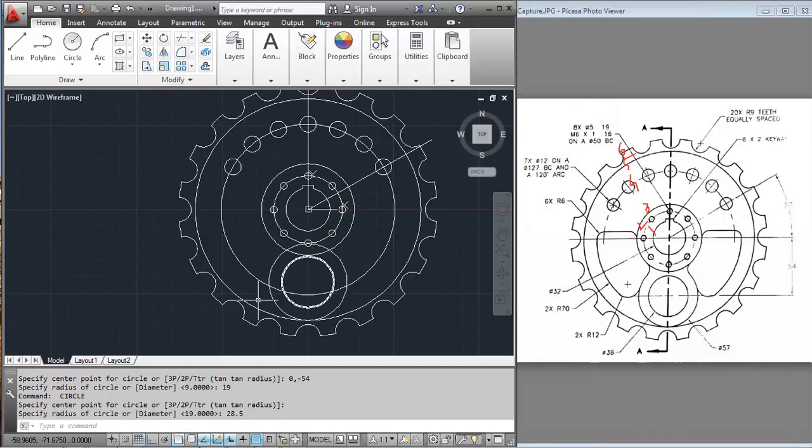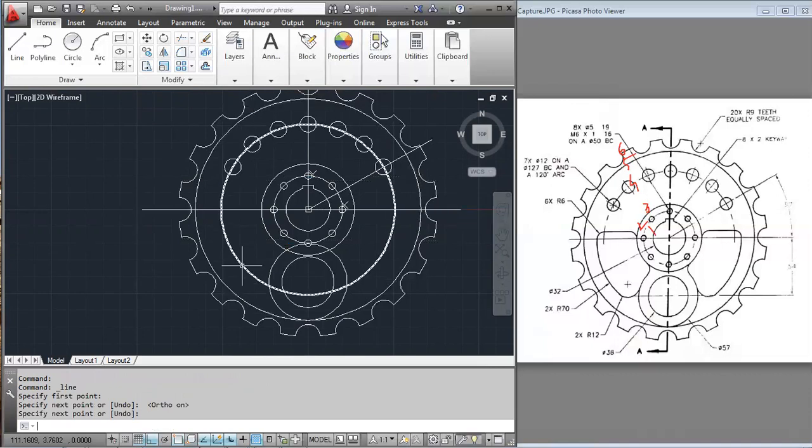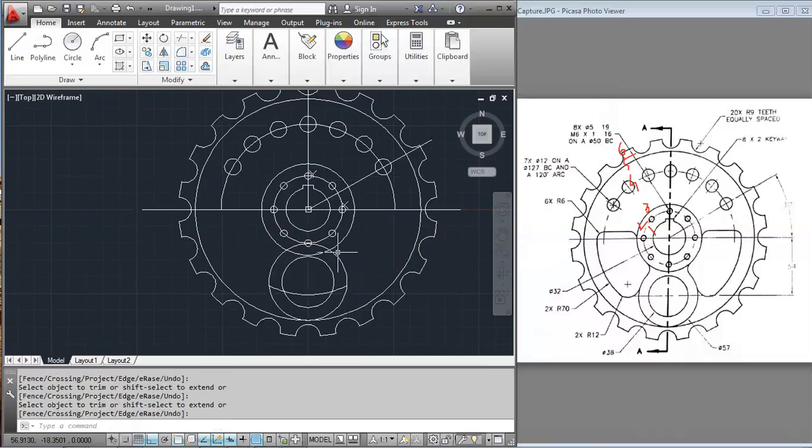All right. Once we get these two, I can just fillet it to match it with them, right? And I do not need it this much. So let's just draw another line. Start it from here. Click on F8 so that I get a vertical line. Use the trim command to erase this one because this one won't be needed anymore. Now from here to here there will be a fillet.